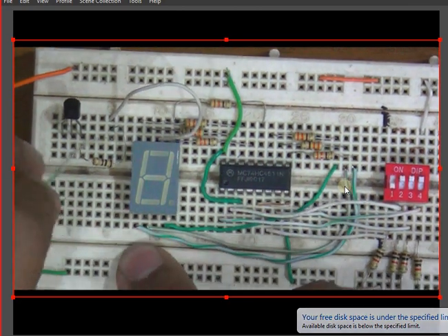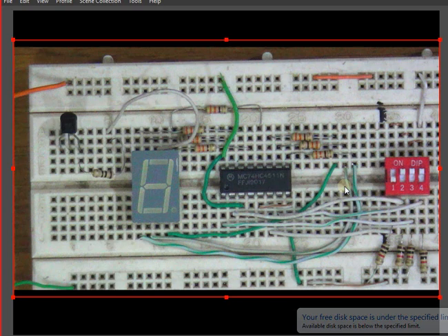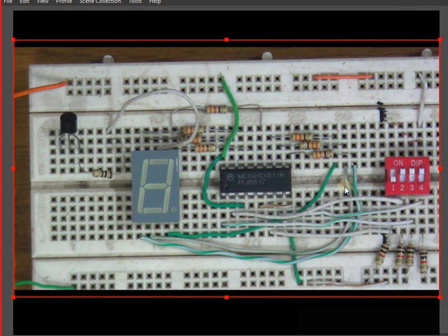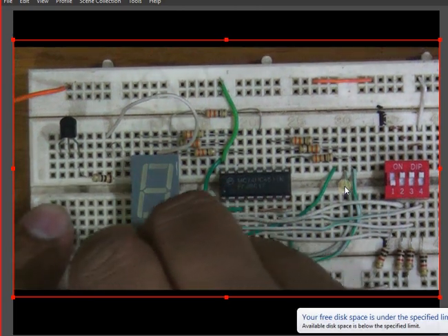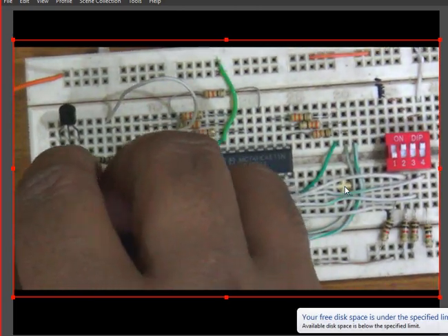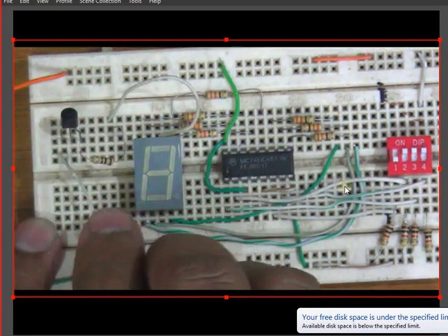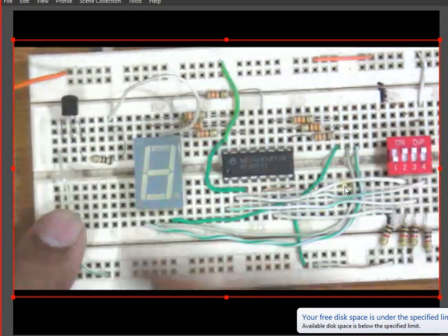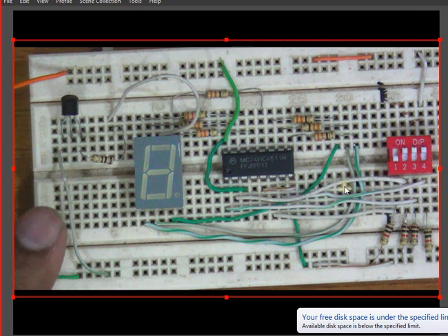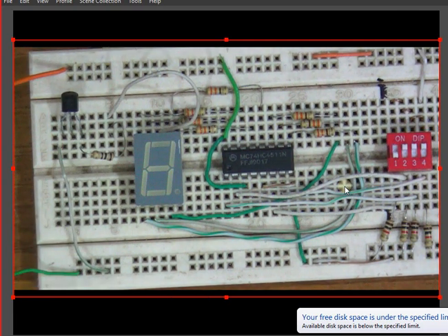In fact, it's not peeled off. Let me just peel it off over here. So this is now going to be peeled off, and I'm going to connect it over here. I'm just placing the transistor over here. Now I want a 1 kilo ohm resistance, and that 1 kilo ohm resistance is going to provide me the base current, so that now I'm going to turn it on.